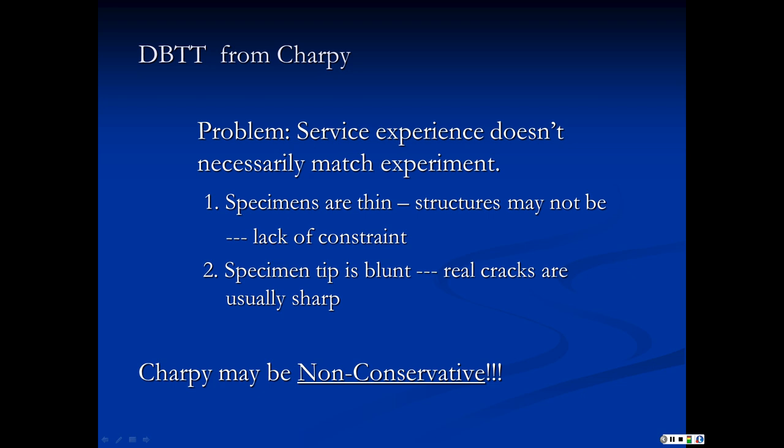Same thing with the notch tip. The notch of the Charpy might be sharp enough to be worst case, but in tougher materials it's usually not. And real cracks, unfortunately, in real structures are usually sharp. So you have to use the Charpy technique with quite a bit of care, because the specimen is not necessarily representative of worst case behavior in the structure.